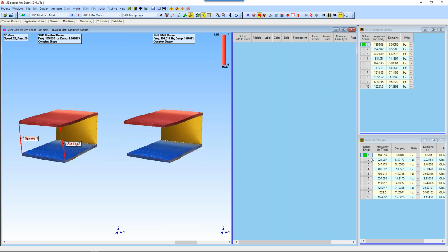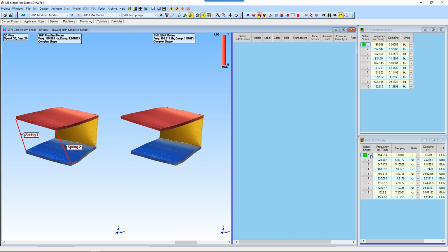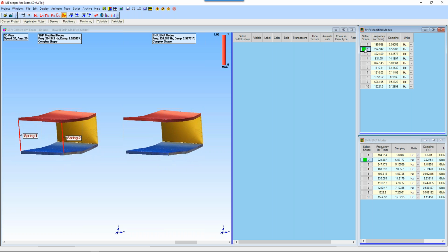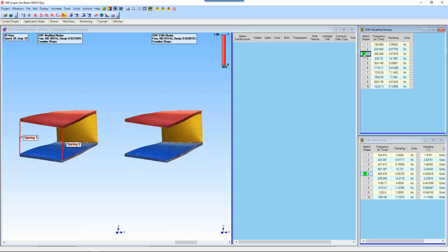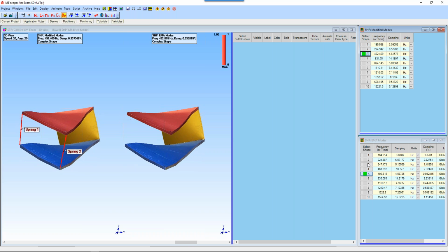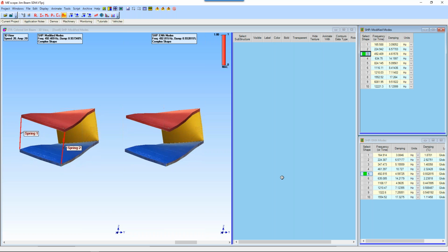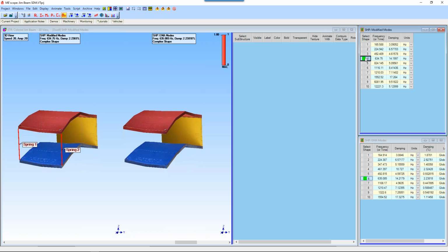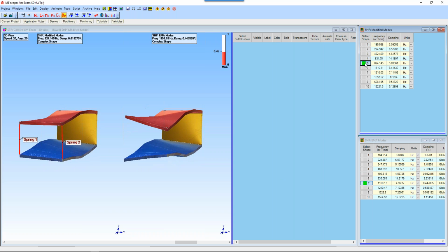165, it's matching up pretty well, 100% with the unmodified 164. Frequency is almost the same. There's another, so those first 2 modes are still there. The second spring didn't do anything to remove them. There's a third mode. It used to be the fifth mode. So two of the modes in the unmodified structure have been eliminated by that second spring. And there's a mode that's still around. Those two springs didn't change anything.